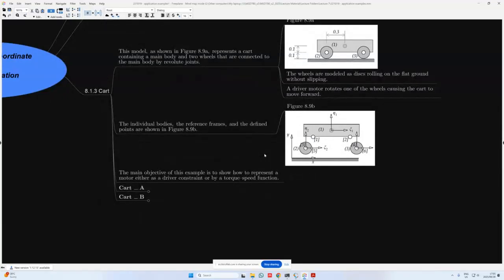In today's lecture, we're first going to focus on Part A and B, and in this case, these will be the inverse dynamic analyses that we consider, or the case where we specify a driver constraint on the system. So where we have some sort of a known velocity, angular velocity or angular acceleration curve, and we want to obtain or measure the load characteristics of these inputs.